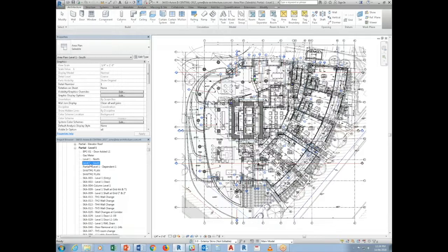I noticed in several projects where users put callouts in a 1/16 plan for their detail, and when I try to find it, it's very difficult. I'm noticing that this callout appears in this view, and no other views are going to exist. So that's the disadvantage of using simply callout. So I'm going to show you how I do callouts in, let's say, this large project.